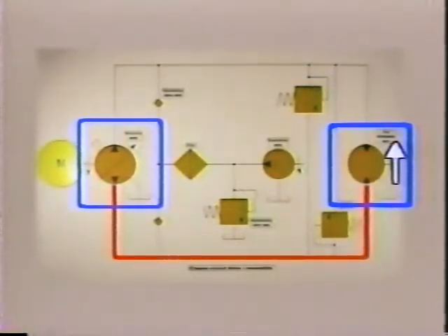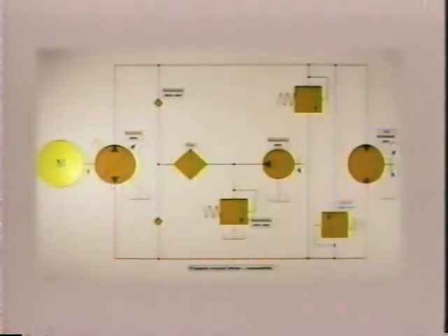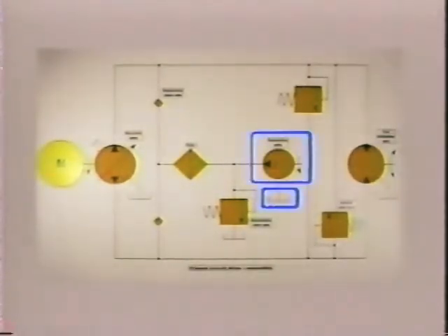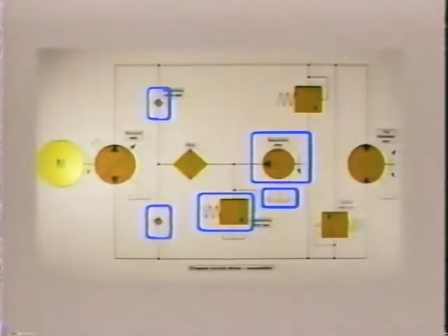So far, so good. But since this is a closed loop, all the oil the pump receives is what returns from the motor, and this could cause problems. As good as they are, both units do have some internal leakage. Adding a small reservoir, pump, and relief valve would enable us to replenish the fluid leaked from our closed loop. But since our system is reversible, we'd need a check valve here and another here. And these are called, you guessed it, replenishing check valves.